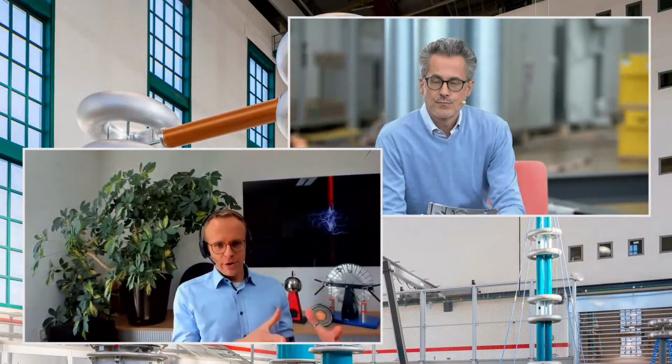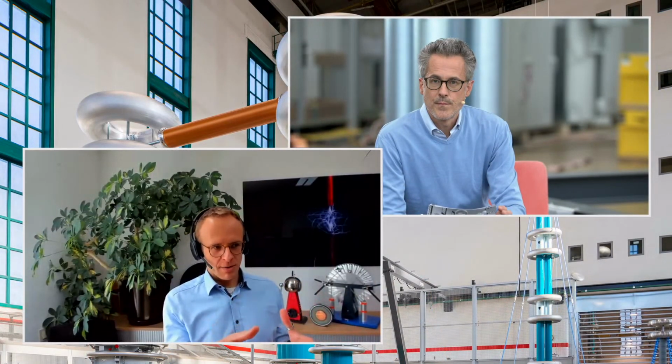Yeah, that's a good question, because now we are talking about the difference in basic research. This is usually done, as you said, on thin film material samples, or material samples at all. And then we have to transfer this knowledge to real insulation systems. In my eyes, simulation models are the key in the design of these insulation systems. And these simulation tools we must feed with the material parameters gained from laboratory sample measurements.